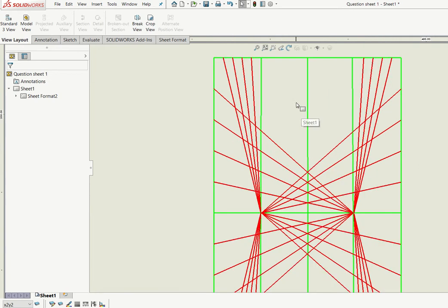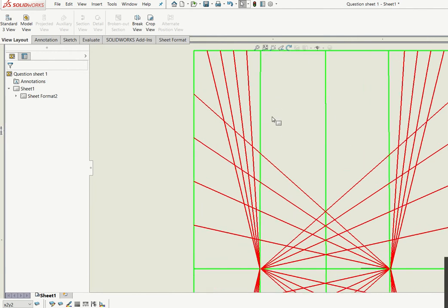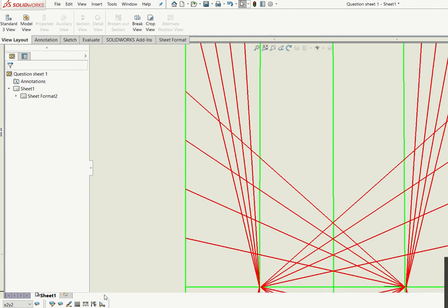Okay, so like I was saying here, we're going to divide this up into 5 equal segments, and we're going to divide our left side up into 5 equal segments. Now once we have this done, we want to join it to our two vertices. So our top points are going to join down to vertex 1, and our points on the left are going to join over to vertex 2. Now where these lines intersect are going to give us points.